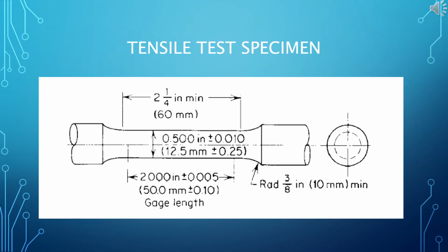Here are the design specifications for a standard tensile testing sample. This one is a dog bone design seen commonly in ASTM standards with a circular cross-section. The ends are threaded, so they may easily be screwed into the tensile testing machine grips.